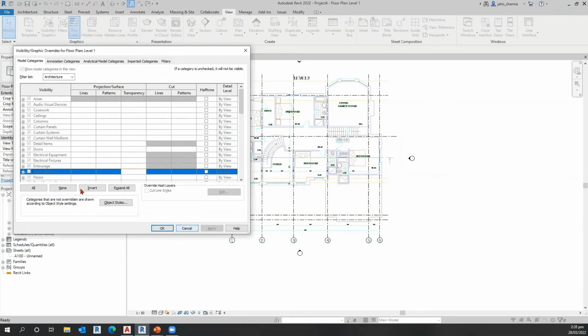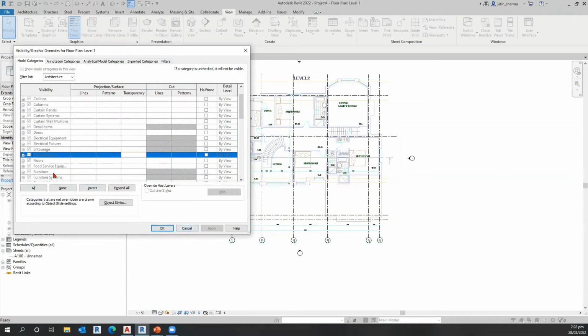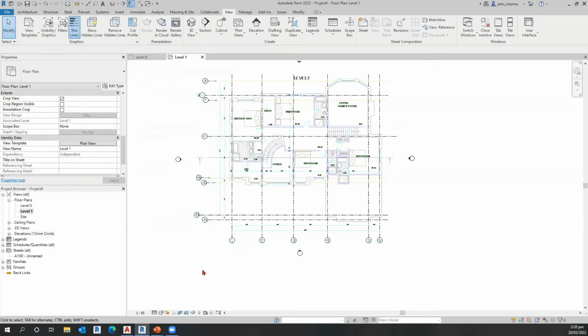So what you're doing is grabbing that ability away from users that aren't as well versed in Revit and making sure that it's consistent across the board, so that anyone who's working on projects that you're involved in, if you have these view templates, then it's all there for your users. They're not having to make any changes, and perhaps you don't want them to make changes, whatever the case may be. But essentially, you're introducing a level of consistency across your projects over and over again, which is super, super useful.